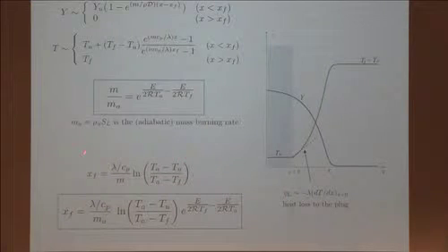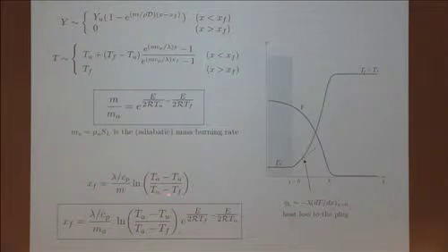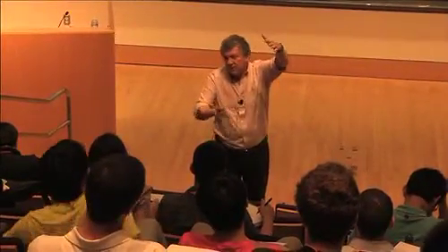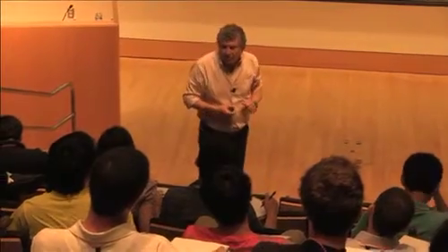By the way, note from this expression above the framed one that when Tf approaches Ta, you get the log of 1 over 0, which is infinity. It's negative, because 1 over 0 is negative infinity, but this is a negative quantity. Anyway, it approaches infinity, which means that when the flame temperature approaches the adiabatic, the flame will be sufficiently remote from the burner. Infinity means the burner essentially has no effect on the flame. That's what you expect.